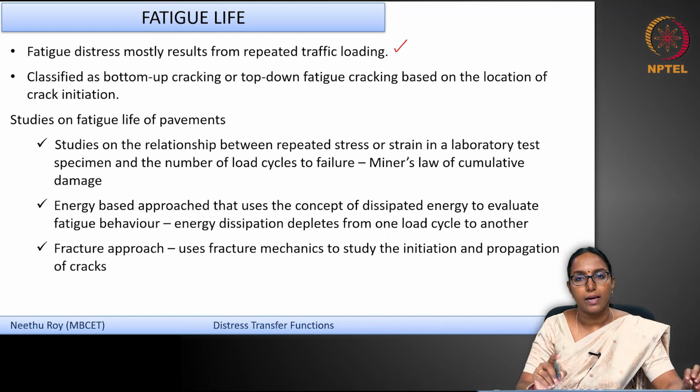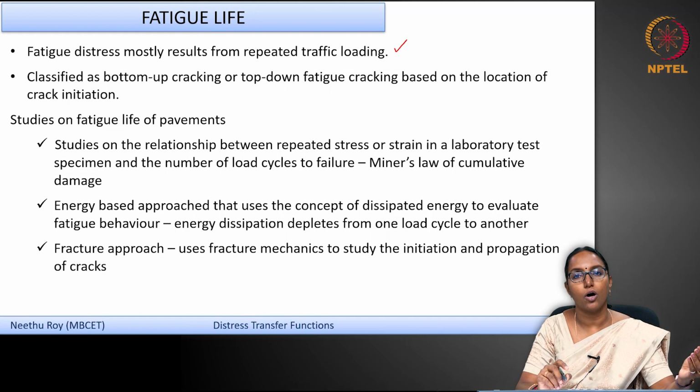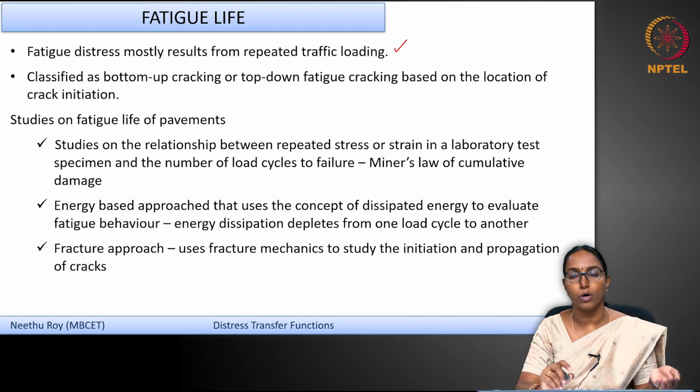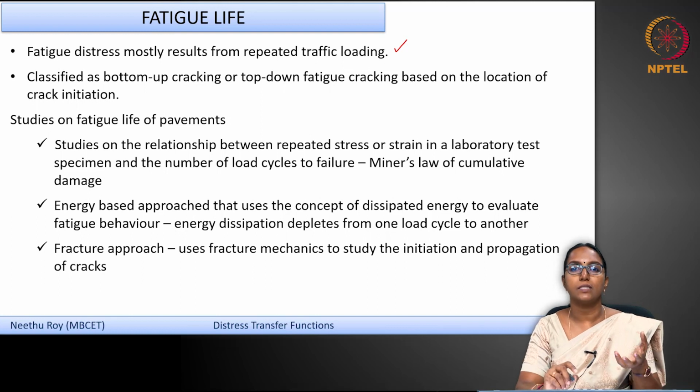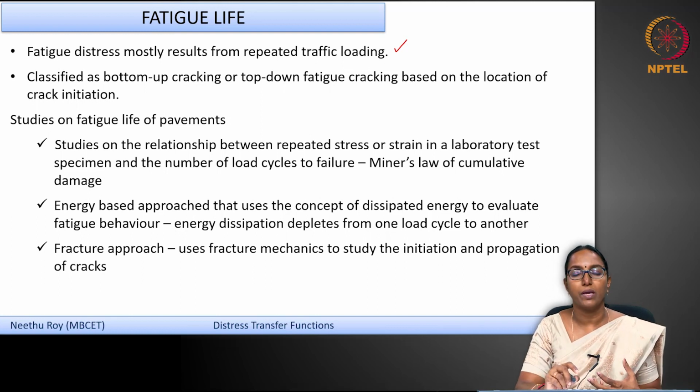Now the cracking that you see on the surface could be a bottom up cracking or a top down cracking, based on where the cracking has initiated. If it initiates from the bottom of the bituminous layer and propagates up, you call it bottom up cracking, or if it starts from the top surface and propagates down, you call it top down cracking.